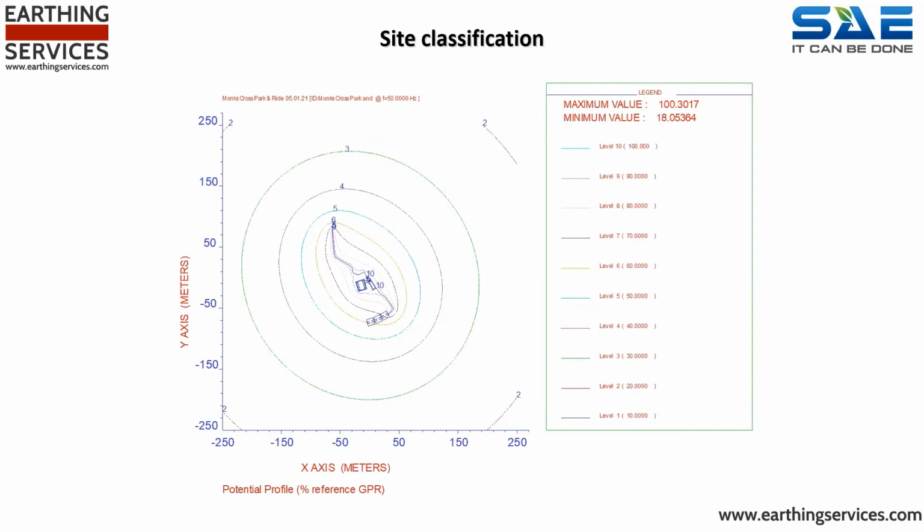A cold site relates to requirements in Engineering Recommendation S36 Issue 2, 2018. A return of earth potential, ROEP, of less than 430 volts can be considered cold. Anything exceeding this will be considered a hot site, which may require additional steps relating to separating HV and LV earthing provisions. The ROEP in this case study was calculated at 413 volts. Therefore, it's classified as a cold site.